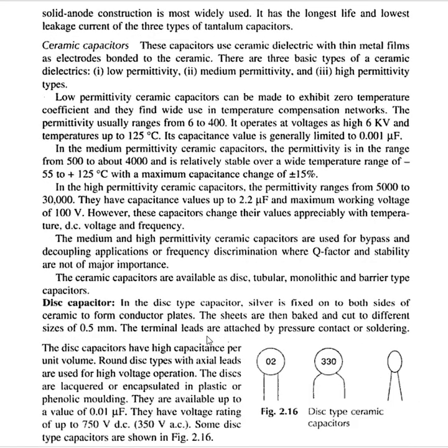Ceramic capacitors use ceramic dielectric with thin metal films as electrodes bonded to ceramic. There are three basic types of ceramic dielectrics: low permittivity, medium permittivity, and high permittivity types. Low permittivity ceramic capacitors can be made to exhibit zero temperature coefficient, and they find wide use in temperature compensation networks.